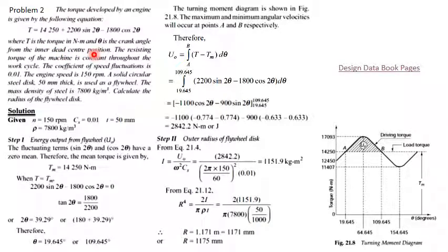The maximum stress occurs at r equal to 0, and this value can be computed by putting the values of rho, v and Poisson's ratio mu. Now mu is given to us as 0.3. The peripheral velocity v can be computed as omega into r.